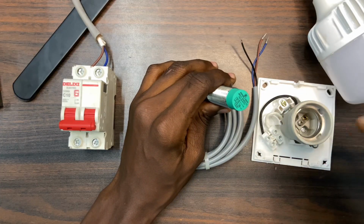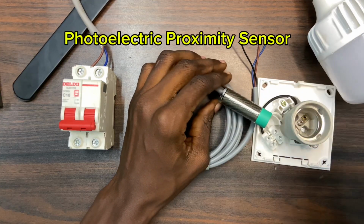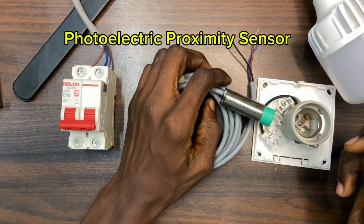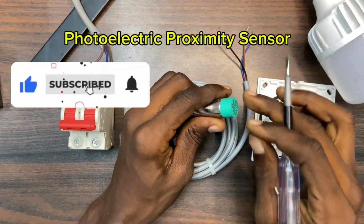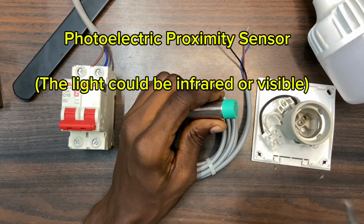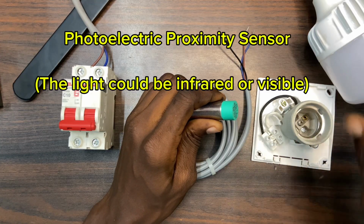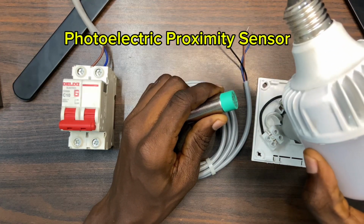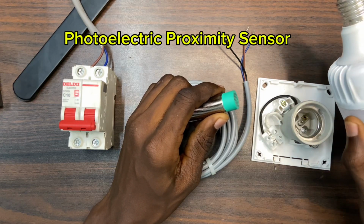You also have the photoelectric proximity sensor. Now, this photoelectric proximity sensor uses a light beam to detect objects. You could see that there's a light over here when the sensor is active. That is the photoelectric proximity sensor. When an object comes into contact with the light, then it activates or deactivates a circuit.